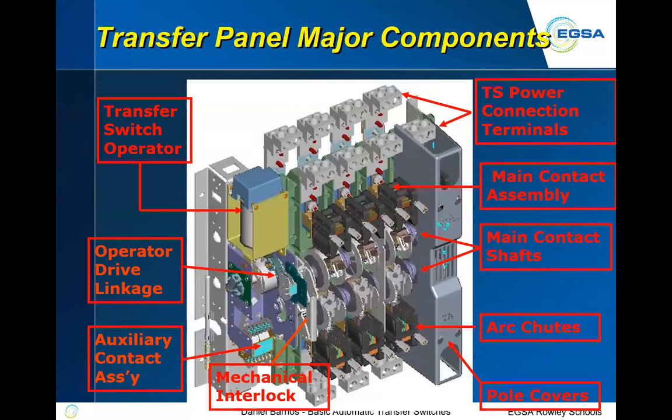You'll notice that those terminals at the top, as I said, are kind of goofy looking. They look like a clover in some respects, so that you can put either two of one size cable or one large cable. Those are very well defined. You can look at the mechanical installation drawing of all of your transfer switch manufacturers, and they will specify the range of conductors and what type of terminals they are providing.